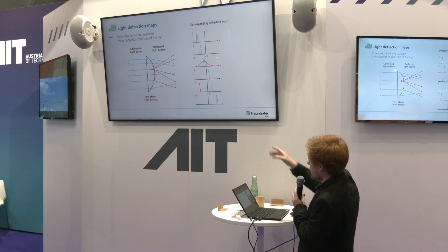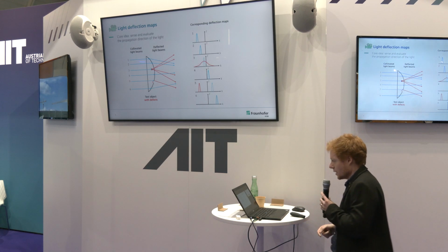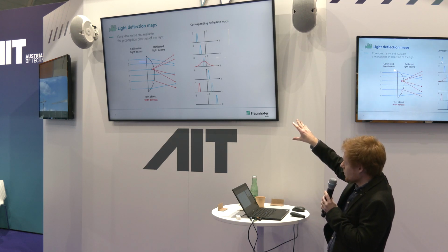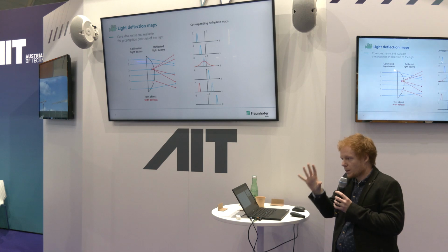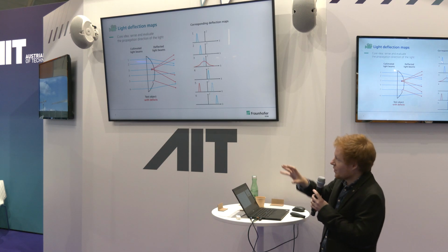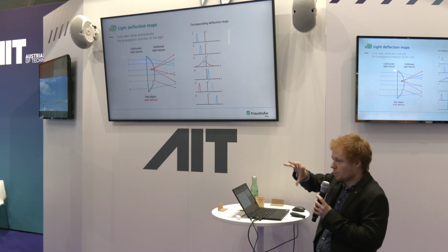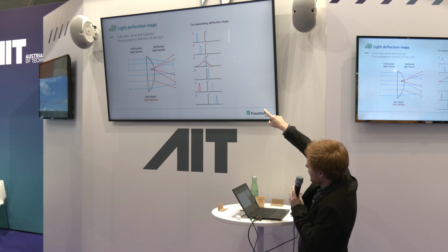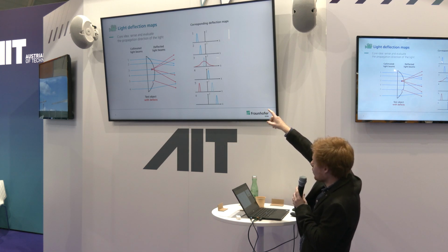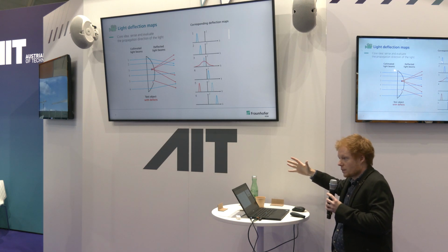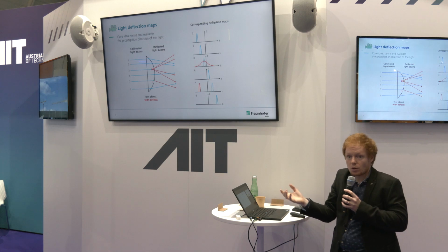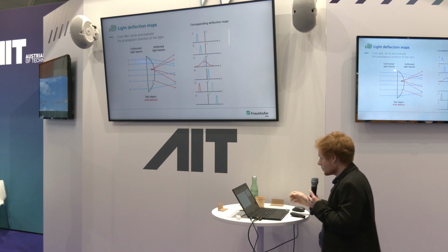And finally, we have a defect-free position again. So the idea now is to acquire those deflection spectra for our complete test object, and to find discontinuities between adjacent deflection spectra. That is, we want to find positions where we suddenly go from a peak to this broad deflection spectrum, or where our peak is suddenly moved to a completely different position.